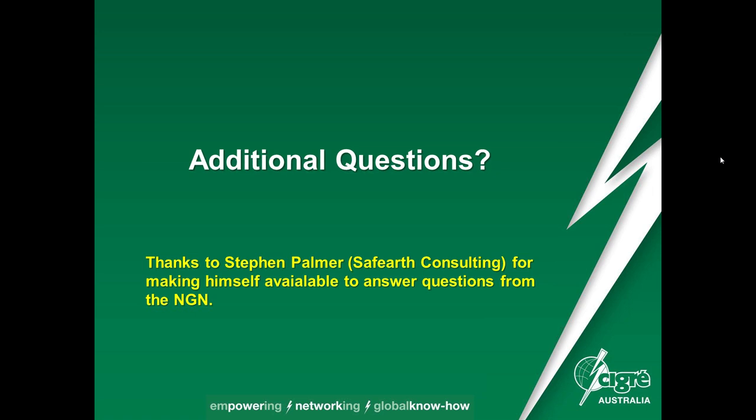Hey Steve, thanks for the presentation. It's been a very thought-provoking and interesting discussion. My question is a bit of a follow-on from maybe the first two, but with the changing standards, we're seeing a transition now from the IEEE 80 sort of flatline standard to a more risk-based approach. With that transition, a lot of the substations that were once safe may become unsafe and vice versa. In my very limited and probably naive experience, we don't really review the performance of an earth mat until we have to. So until we're going to do some augmentations on a site or some additional work, and we need to ensure that substation's safe.